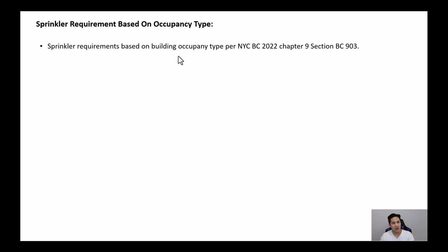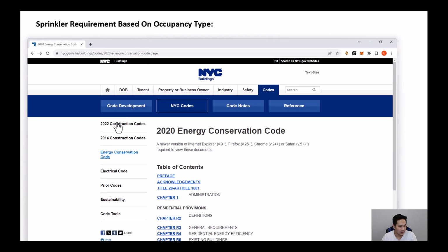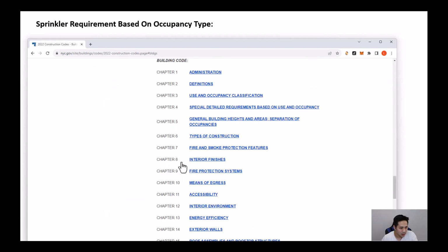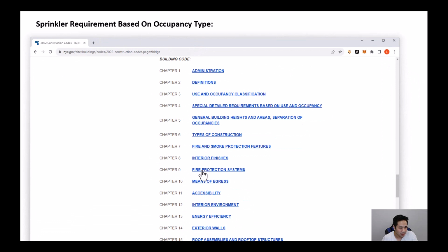Sprinkler requirements based on occupancy type are per the New York City Building Code 2022 at the time of this video, Chapter 9, Section BC 903. If you go online to the New York City site here, you can type in the latest code. At the time of this video it is 2022, but you have to use the current version of the code for your project. So for 2022, you could go to the building code here, and Chapter 9 is right here, and it's the fire protection systems chapter.